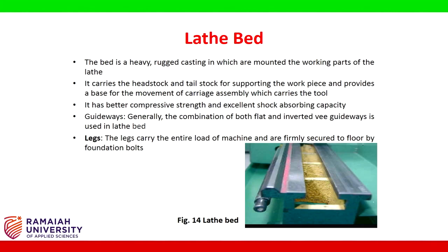It carries the headstock and tailstock for supporting the workpiece and provides the base for the movement of the carriage assembly which carries the tool. It has better compressive strength and excellent shock absorbing capacity. Guideways. Generally, the combination of both flat and inverted V guideways is used in the lathe bed. Legs. The legs carry the entire load of the machine and are firmly secured to the floor by foundation bolts.